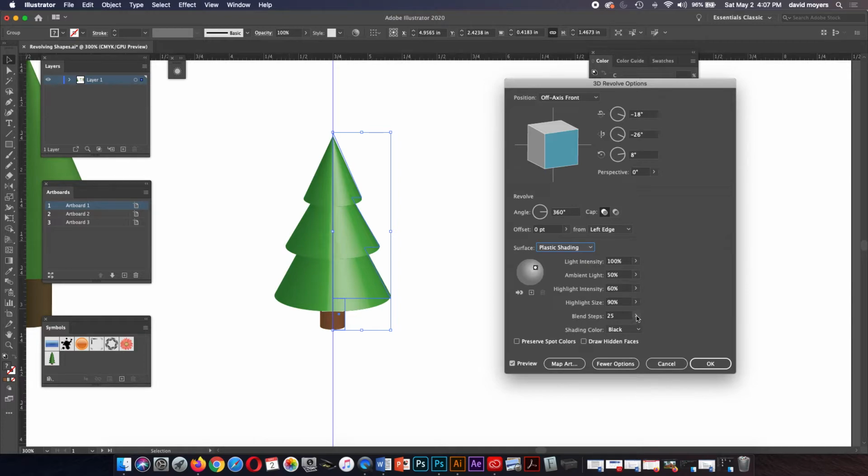This technology that Adobe has created is actually based off of blends and not gradients, and we know what blends are. So what we need is to increase the blend steps so it's a little smoother. See that? So when you have an object you have revolved, if it's choppy, then you want to up your blend steps as much as possible to get a much smoother result.